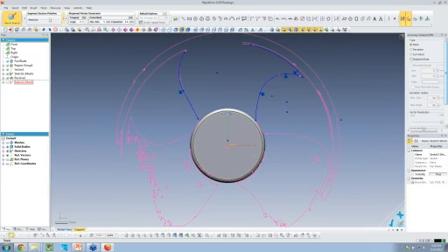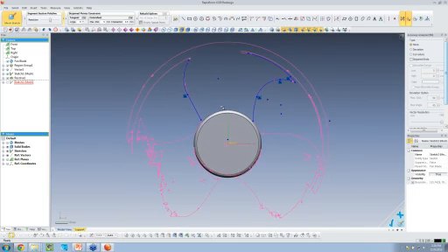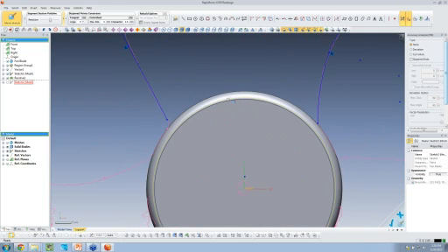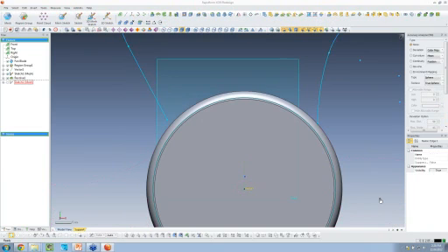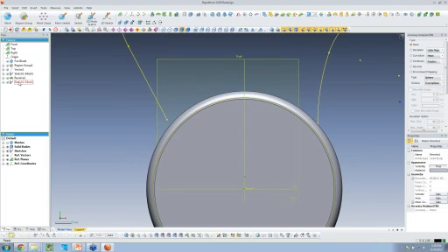Okay. Since I want this part to go inside of the model, I can also select features on top of my existing CAD, and I can convert those into entities that I'm going to sketch. Now I know I'm concentric. I know I'm always evened up with that particular feature. Oops, got out of my sketch mode.